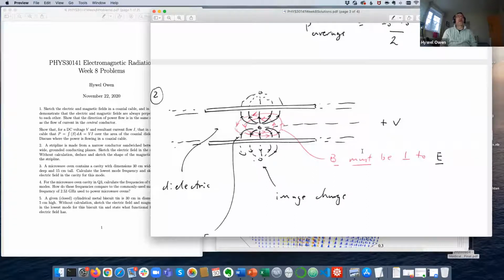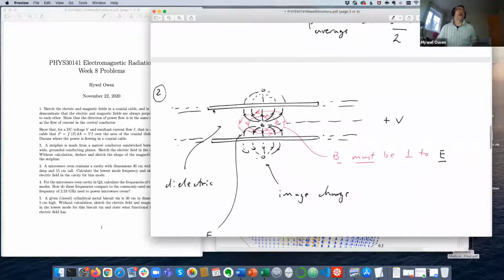The traditional strip line has two ground planes. The way in which the strip line is made is by basically taking a coaxial cable and then flattening it by banging on it so it's all flattened out. So I still have this conductor in the center, and as a first approximation, the sheath has been flattened out, so it forms two layers which are flat above and below the central core. So this is what's meant by a traditional strip line. You can see here that approximately we can consider the ground layers to be large flat surfaces which lie some distance, equidistant from our central conductor.